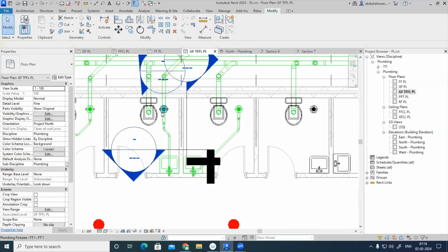we need separate floor trap. Correct. So you can't avoid a floor trap with it, because the floor trap will be acting as a floor drain as well. You don't want to propose a separate floor drain. The floor trap grating will be acting as a floor drain as well. So that is mandatory. Even if you're not having a wash basin within the toilet cubicle, when the water is accumulating on the floor level, you have to sweep it. So floor drain you can propose, but without floor trap cost is, because if you're not having any wash basin and all, it is not mandatory sometimes, the floor trap.